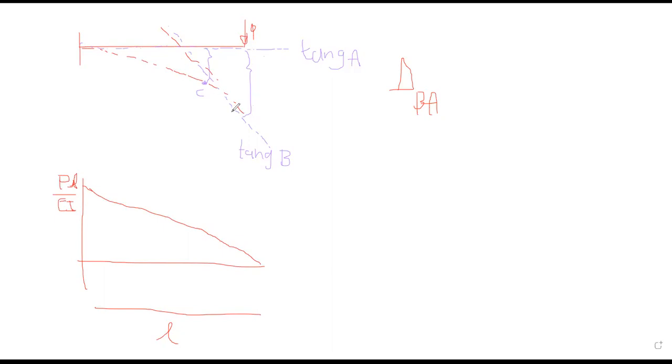The theorem itself shows the vertical intercept between two tangents drawn from 2 points along the elastic line. So it is not deflection. Why? One of those is not horizontal, right? But what happens if one becomes horizontal? That means we know theta is 0, right? So then we can take it, it is the deflection at B.